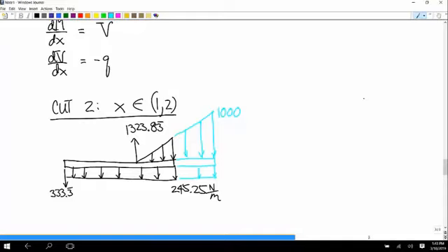And then what other loads are applied? The internal loads: tension, shear, bending moment, and torque. And now that we've chosen a body to isolate, we can represent these distributed loads as point forces. So let's talk about those.